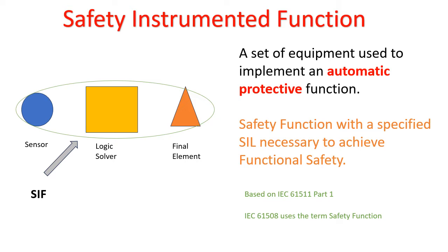In simple words, a set of equipment used to implement an automatic protective function is known as a safety instrumented function. As you can see in the figure, a sensor, a logic solver, and a final element basically constitute a SIF. But that's not all.